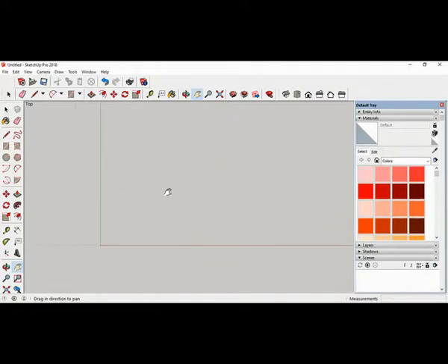Here we are going to start the drawing. Let me open that drawing. Okay. So this is my red. This is green. Don't worry about that. First, let me use the tape measuring tool. Just parallel to green, I draw one line. Parallel to red, I draw. So this is my building corner.